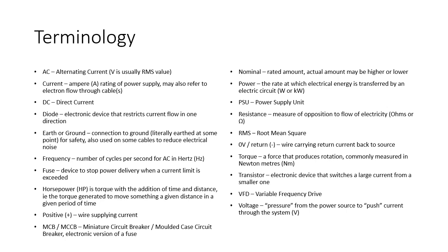DC is direct current. There is DC inside the VFD. We convert AC to DC, and then we can convert the DC back to AC again. So that's the function of the VFD, to do that conversion. And the reason for doing that conversion is so we can change the frequency of the output.